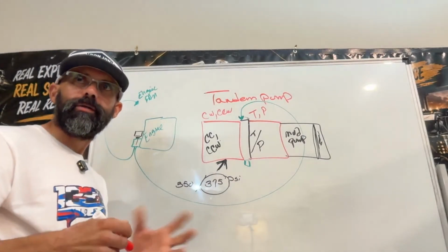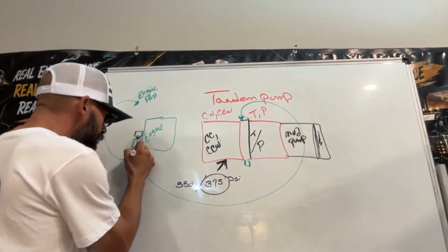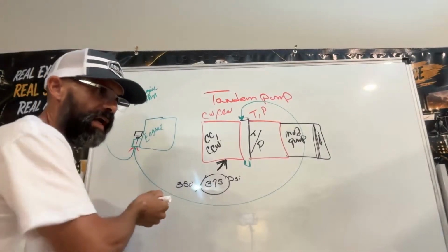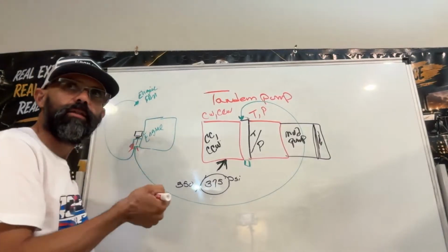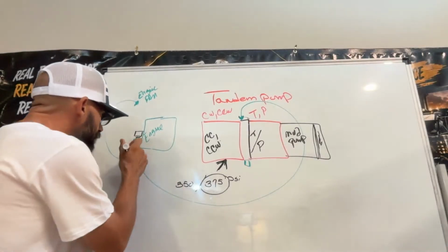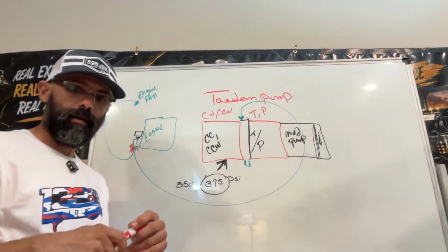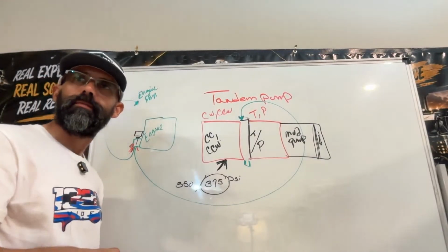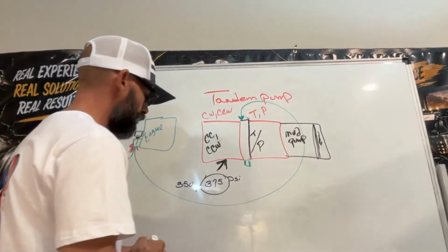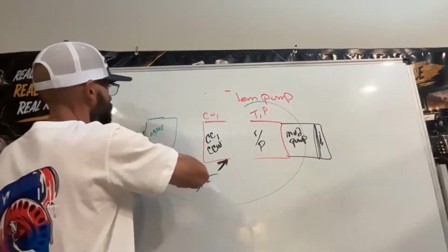Remember the pump that is underneath the alternator, that always has these fittings right here leaking because they get over tightened. They go crazy tightening the fitting on an aluminum housing, and they end up cracking the housing where the threads are. That's why they leak. That's why I said if you gotta use a magnifying glass, use it, because they think, oh no, it's the O-ring, because it's a Boss O-ring. Let me erase this.